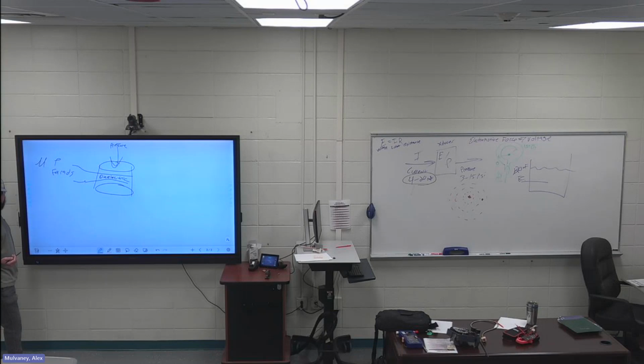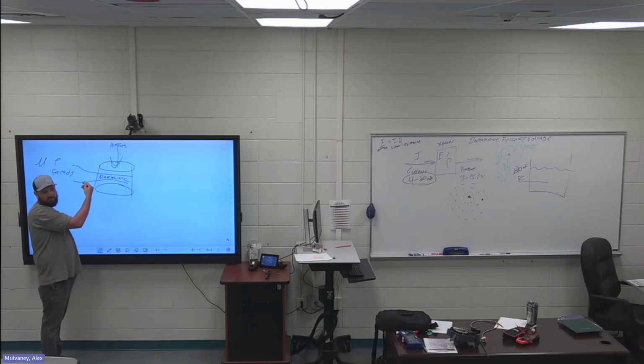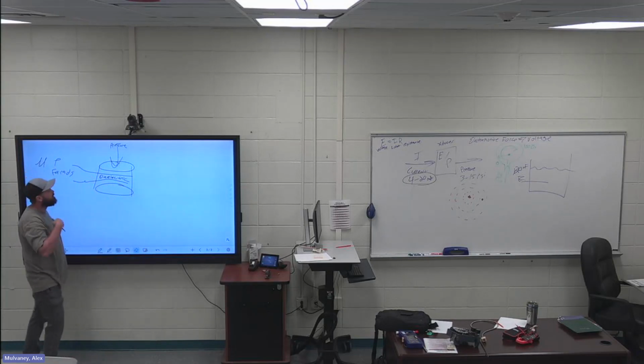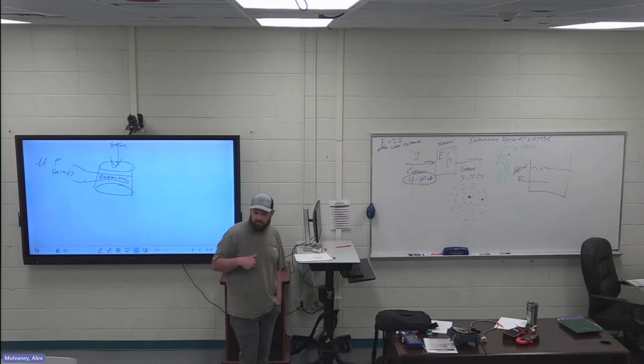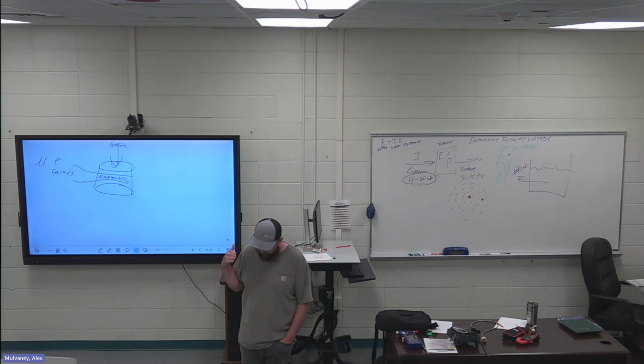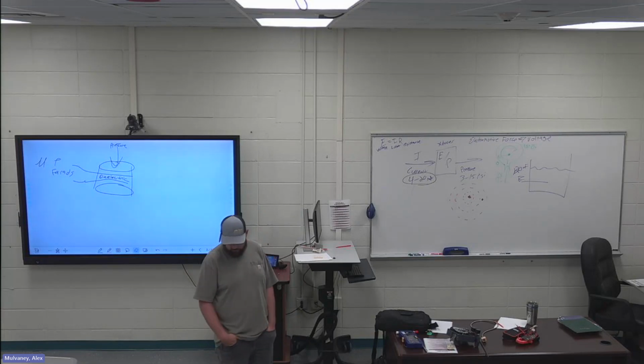So is this an inferred or a direct measurement? Inferred, because I'm measuring pressure, outputting a capacitance to determine a weight or a pressure. Kind of weird. I guess I'm measuring capacitance to determine a pressure. But it's how close those plates are together that changes the capacitance. Okay, nothing is highlighted in 2.5, but I need you to know that for level detection. So we're going into level detection. First thing is we're doing capacitance type level detectors. The first sentence is highlighted, the answer to my question earlier: the capacitors consist of two conductors separated by an insulator. Two plates separated by a dielectric.